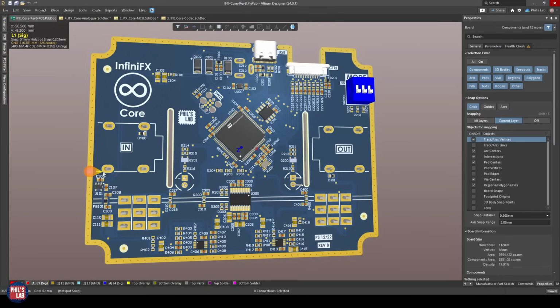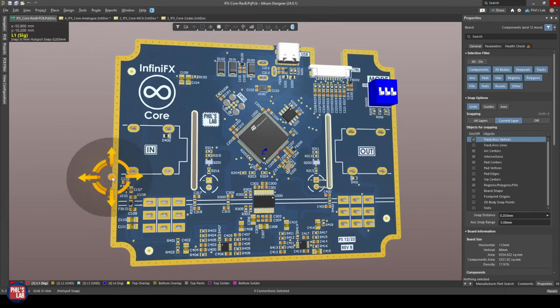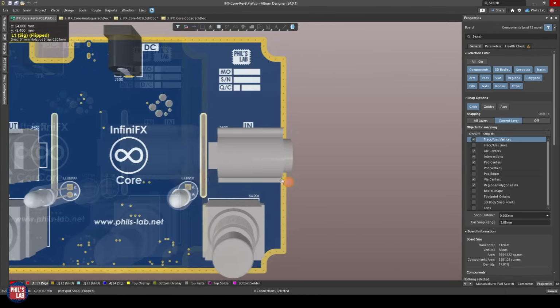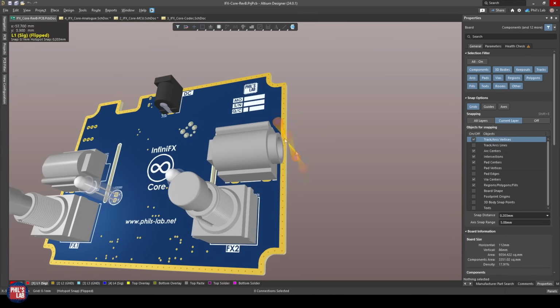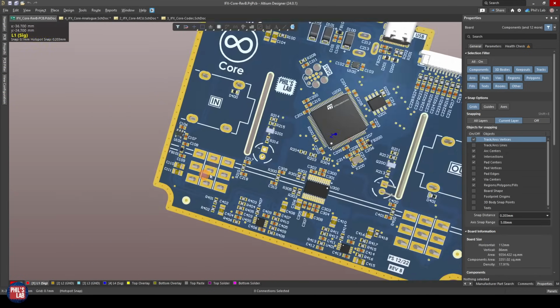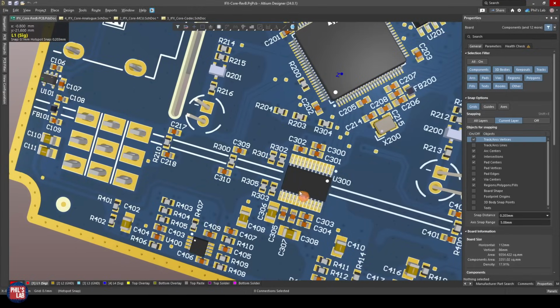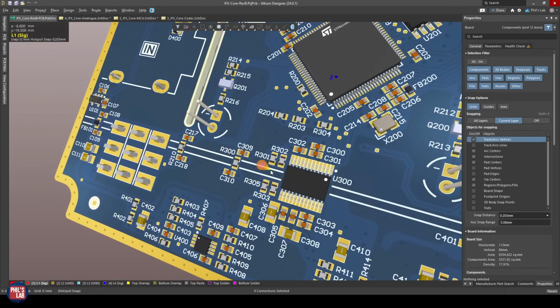The hardware itself is pretty straightforward. It's a 4-layer PCB, components top and bottom. Effectively, I have a 1/4-inch jack on the input, where I can plug a guitar in, for example. That gets fed through an analog front end, effectively just a couple of op amps, filters, and so on to set the upper and lower cutoff frequencies, provide some impedance conversion, and so forth. That feeds into this codec, which is a Cirrus Logic CS4270.